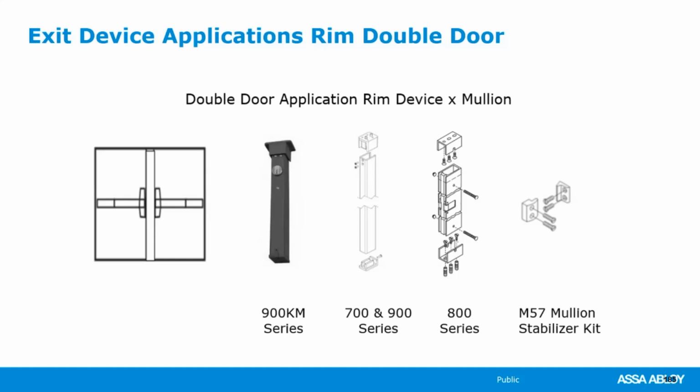And what happens is they determined that with that divided opening, with that center mullion in place, you go to the left of the mullion or you go to the right of the mullion to egress in an emergency. Both doors get open fully and more people can get out. If you don't have the divider in the middle with surface or concealed vertical rods, there's a good possibility that both doors don't get open because people are going to run towards the open area. And that open area is in the very middle.